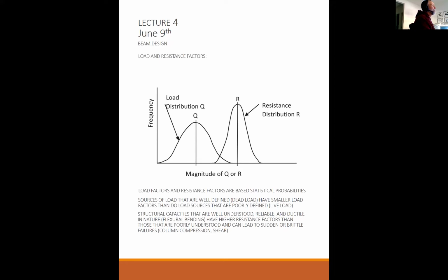And these people were roughly about 2.5 times heavier than the designer of that house had ever figured on. Basically, you design a house, you're designing to 40 pounds a square foot. And these people were pushing about 120, 150 pounds a square foot. So the whole ground floor collapsed and everybody fell into the basement.